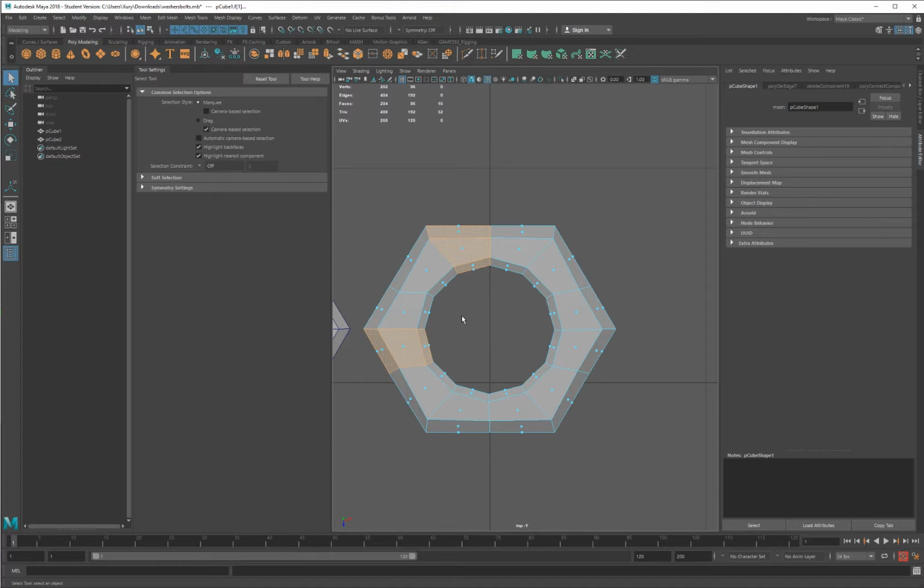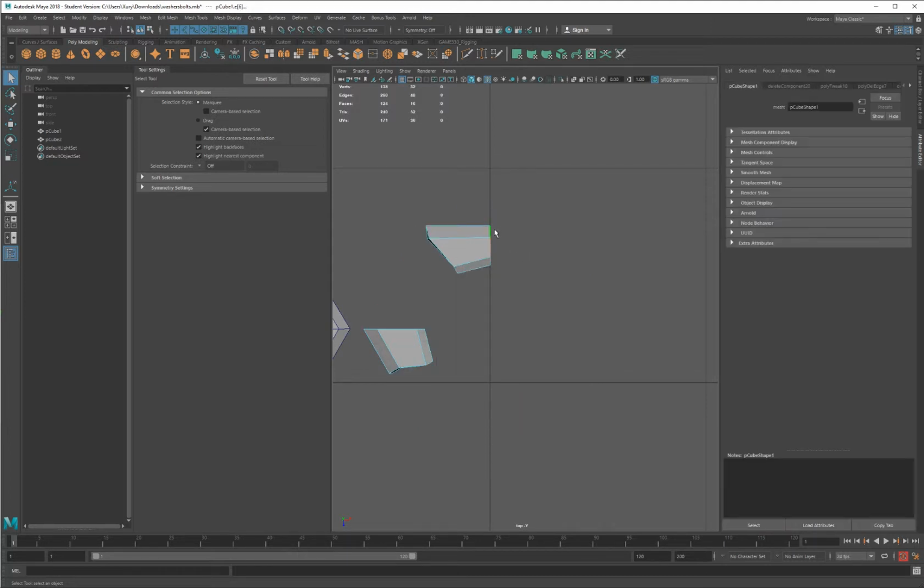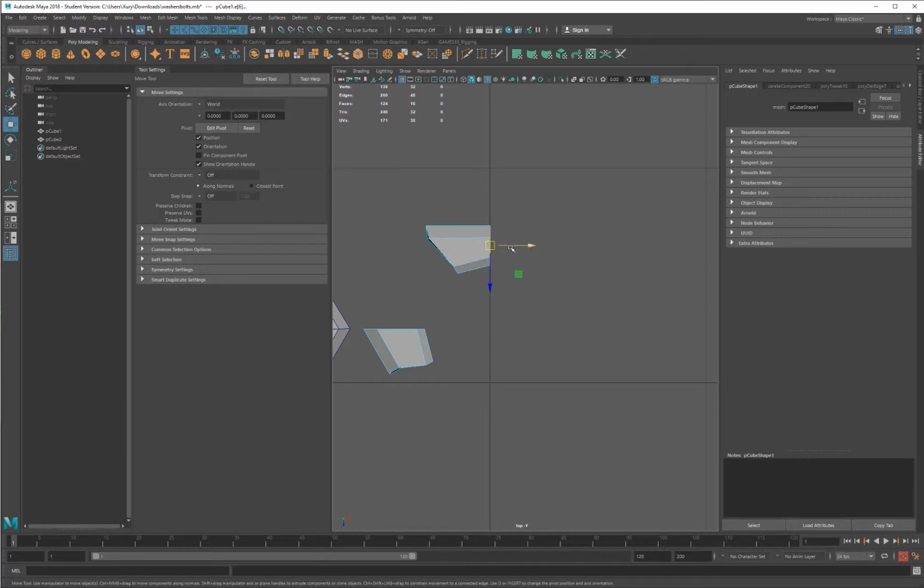And then I'm going to invert the selection. Control Shift I will do that, and then just delete the faces. Then I'm going to go back into edge mode, and I forgot to actually snap this to the grid, not once it was scaled. I want to actually snap it to the grid, so hold X and just pull it that way. It wasn't very far off, but I just wanted it to be essentially perfect there.